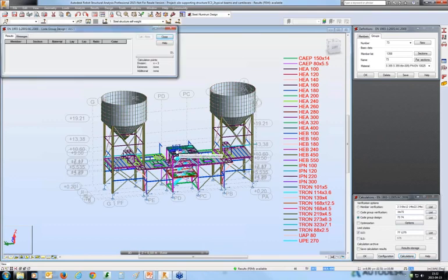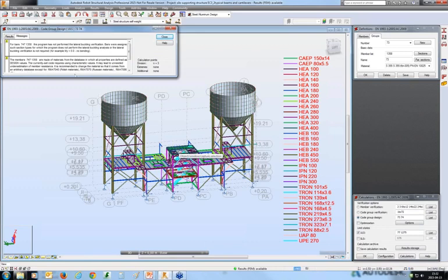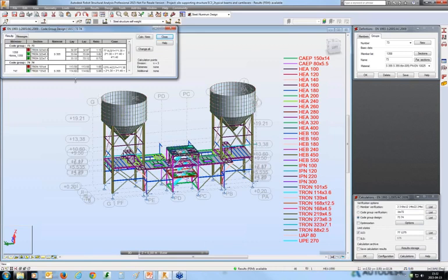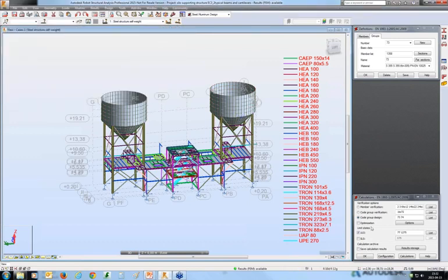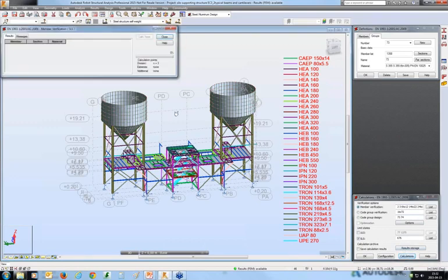So I narrowed my search now to 2 elements. Okay, and that's going to be the same story. I can change the sections and rerun the calculations. That I'm not going to do because it is exactly the same procedure, but instead I'm going to check the sections that I know are correct from the strength point of view. I'm going to check them for deflections or displacement.